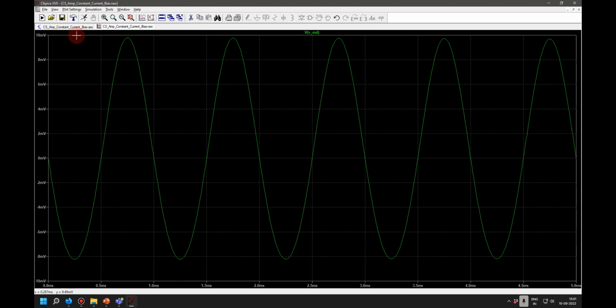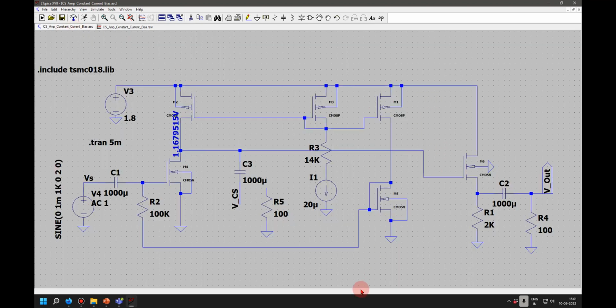Sir, can you show the schematic? Yeah, see. Sir, here M2 is biased in the linear region? No, M2 would have to work as a resistor then, right? It is not in the linear region; 1.2, 1.6 volt is the voltage available. Yes, so when we bias it in the saturation region, we are implementing it as a current source. Yes, current source only.